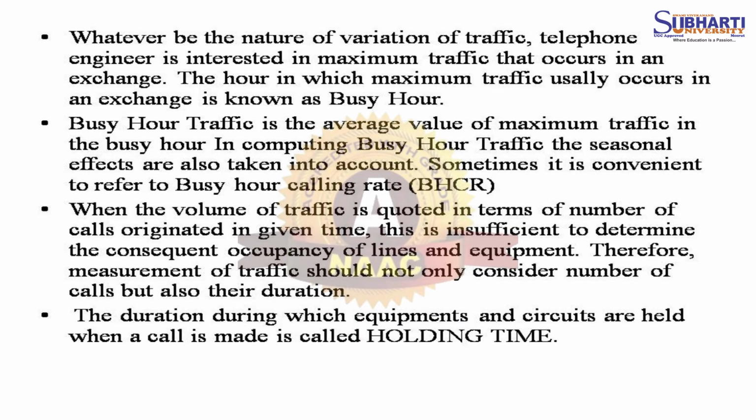However, by the nature of variation of traffic, the telephone engineer is interested in the maximum traffic that occurs in an exchange, but busy hour traffic is the average value of maximum traffic in the busy hour. In computing busy hour traffic, the seasonal effects are also taken into account. When the volume of traffic is quoted in terms of the number of calls originated in a given time, this is insufficient to determine the consequent occupancy of line and equipment. The duration during which equipment and circuit are held when a call is made is called holding time.